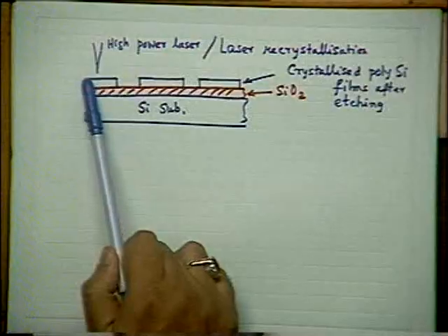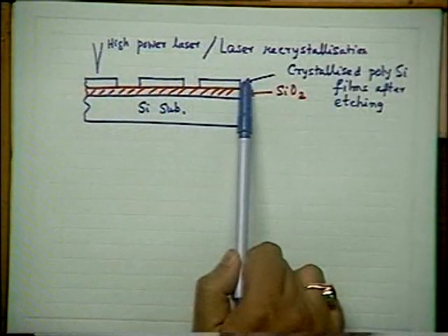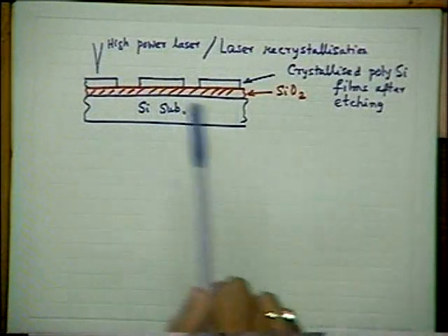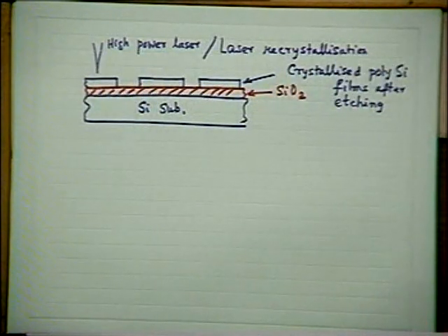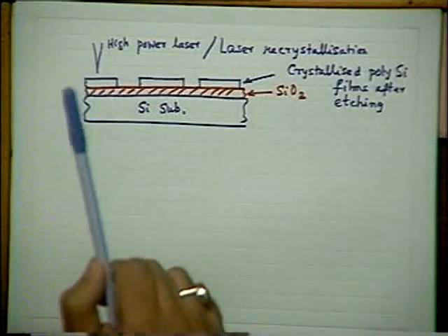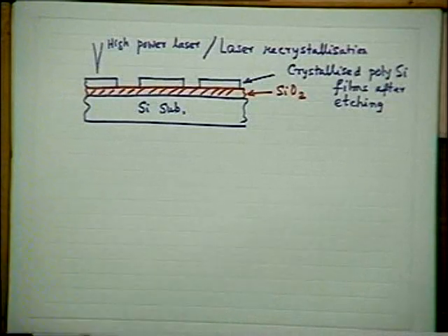Of course, the conversion of the polycrystalline silicon into crystalline silicon, as I told, is by a laser-induced process. There are other processes also. One is from the RCA group, Radio Corporation of America, USA. They developed a technique called moving heater technique, graphite heater. Instead of using a high-power laser, they had small graphite wires, which are red hot, very highly heated by passing electric current, and the wafer sweeps around it like this. By that process also, they reported very good quality wafer, but laser is now more standard than the other technique because of the advantage involved here.